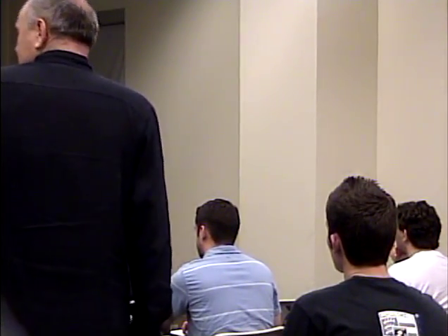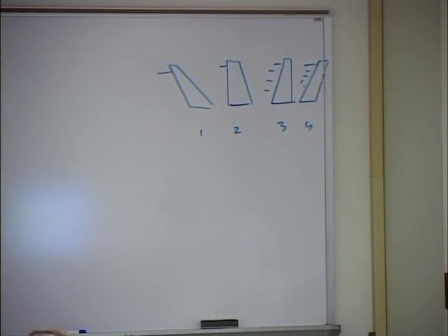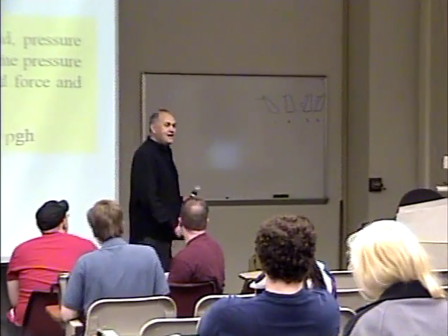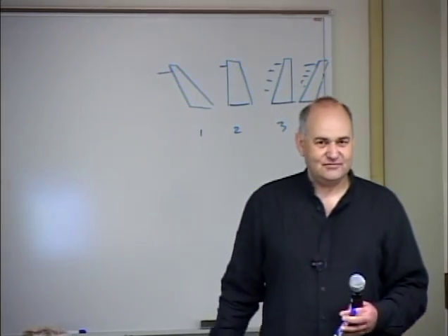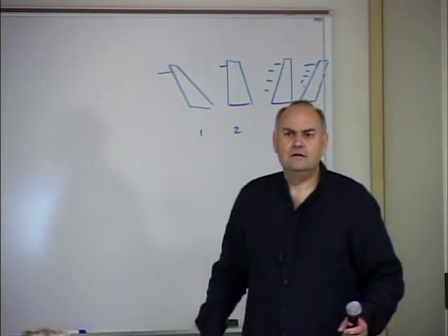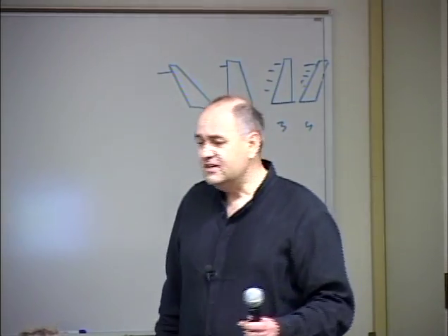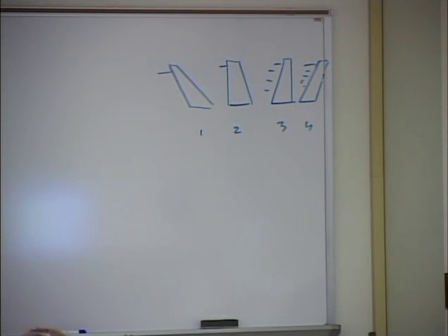Why did you choose 2? Because you thought that it is correct. I was wrong with number 1. What do you say? Aha! Yes, very good. The problem with number 1 is that when the water level goes down, the dam will fall to the left. Why? Because you're reversing your tension and compression force directions. When the water's high, you have a tension force on the inside of the dam. When it's low, that turns into a compression force, since the dam is not being supported by water.